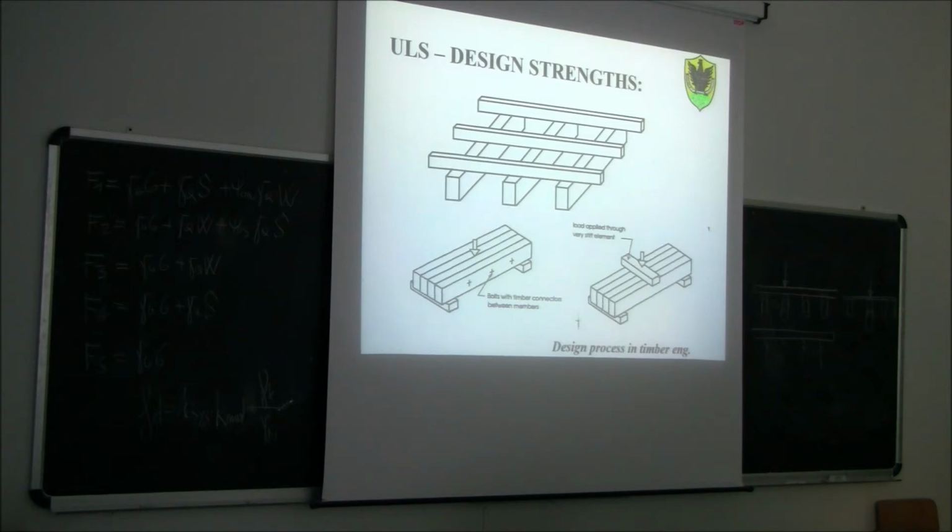So in the end, the situation is much better, because we have a system effect. We have less scatter of results due to the system effect, because the different pieces of wood with different strength are forced to work together, while instead here they work separately.